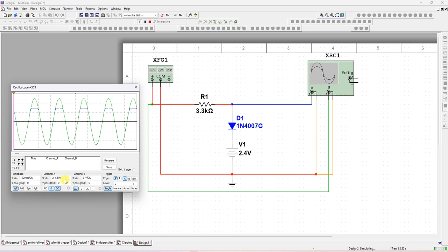For this, it is already there. Click on A to B or B to A. So let me click AB. That is channel A versus channel B. See, channel A versus channel B. To have this channel A versus channel B, please remember A should be connected to output, B should be connected to input. If you are getting the opposite, then click B versus A. Even if by mistake in the lab you are getting the opposite, just change the input and output channels. So you are going to get this.